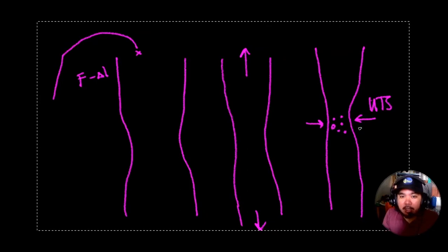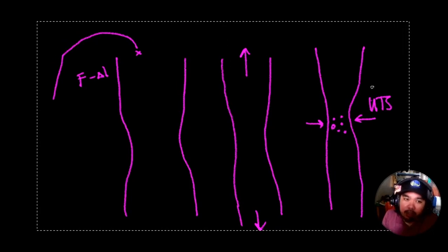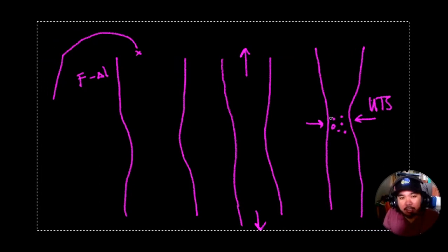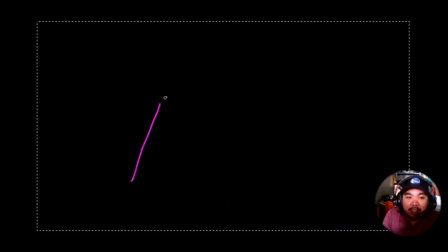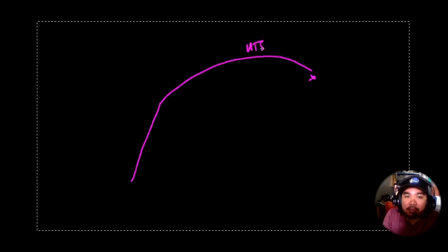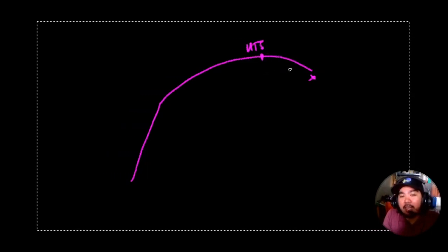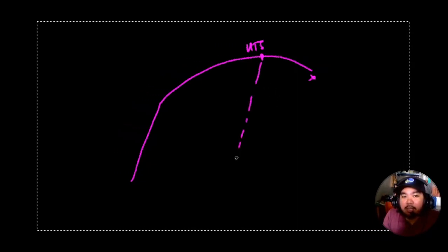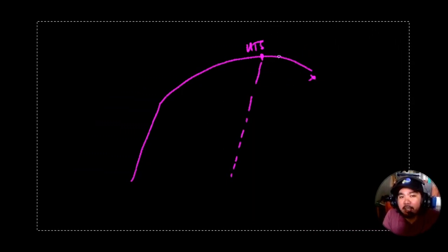So, in that sense, anything past the UTS is not anymore an accurate representation of the behavior of our material, no? Without defects. Because past this, you start having defects. So in a way, its behavior is no longer accurate. To answer your question plainly, anything past the UTS, you can no longer use the parallel line technique to get the recoverable strain. Anything here, its behavior is uncertain.